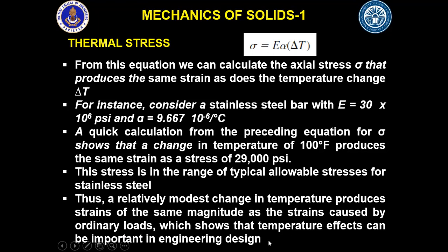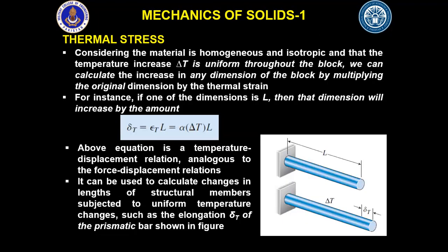So it is very crucial that we do consider the thermal stresses, because if the temperature variation is very low, it is not going to be that detrimental or that effective on the overall strength of material. But if we are talking about heavy and high temperature variations, only then the material is going to have a lot of stress or a lot of strain in it. And because of these things, the engineering design must have temperature effects being taken into account.